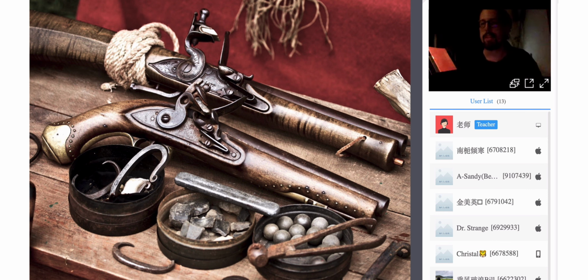So as the hammer goes back, the tension on the spring is increased until the trigger moves past the point, and the tension is released, and the hammer swings back, and it hits where the gunpowder is. Like it hits the chamber where the gunpowder is, and that creates a kind of spark, and that ignites the gunpowder. It explodes, and that explosion is contained within the barrel, which propels the bullet through the barrel at great speed.